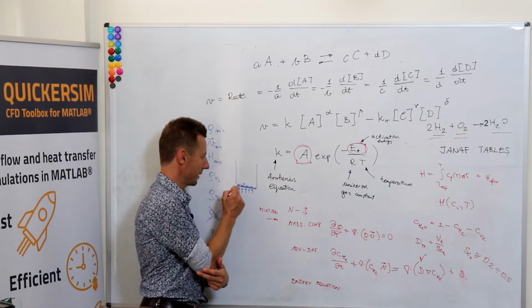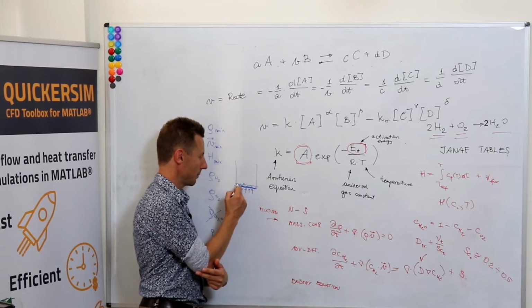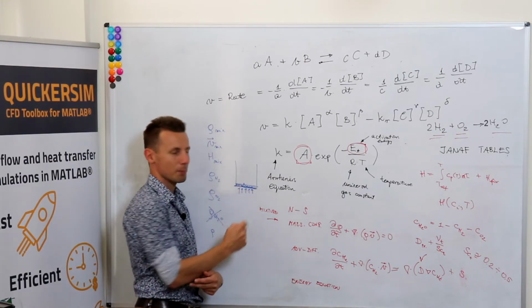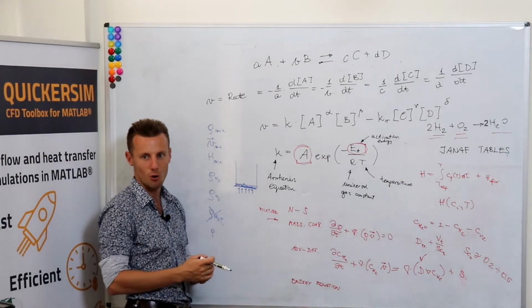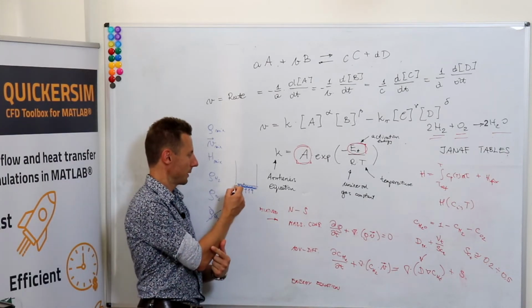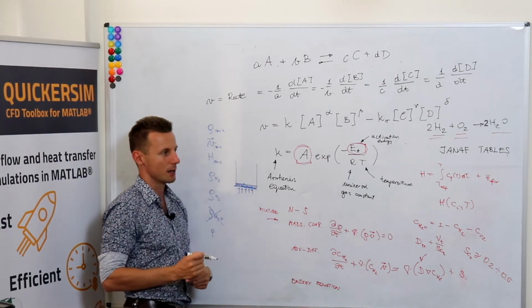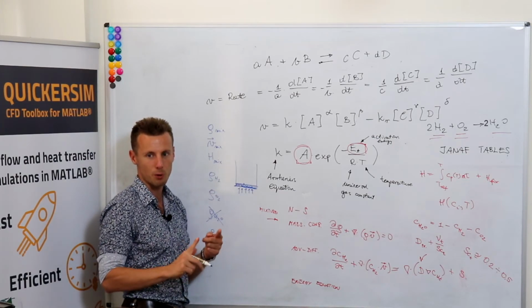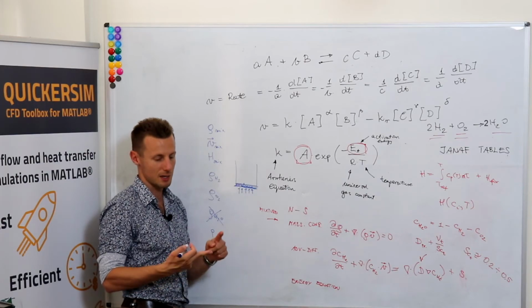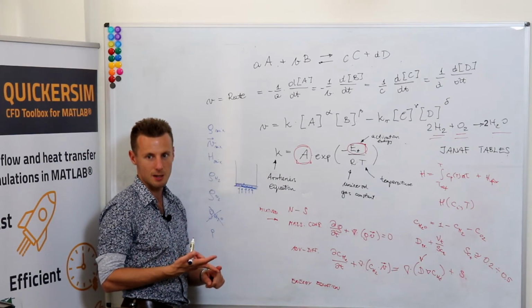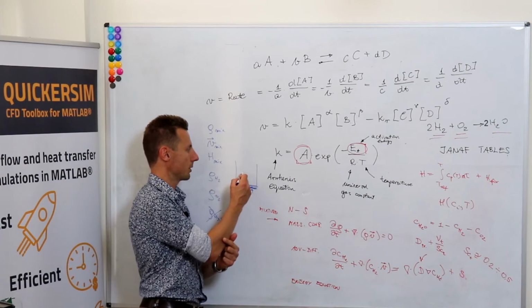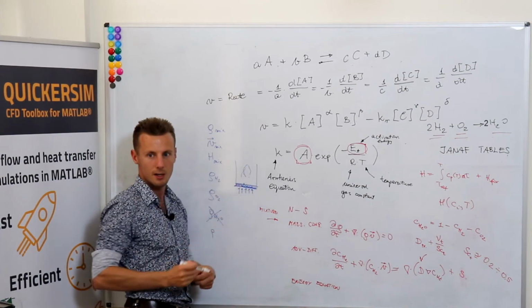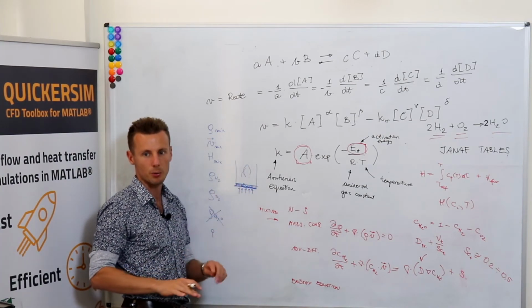And we've been omitting this subdomain in the CFD simulation at all. We have just been imposing the inflow boundary conditions with proper temperature, proper velocity of the gases, and proper composition of the gases. And then we've been modeling the homogeneous reactions of the gas components.